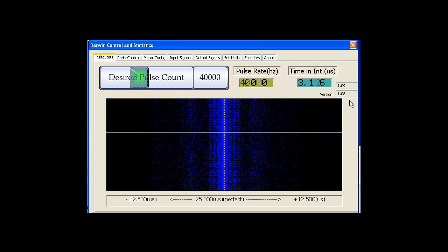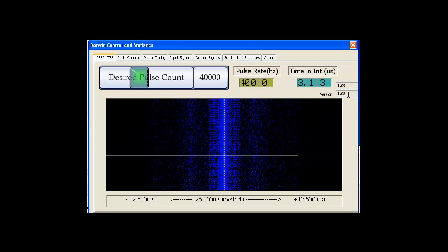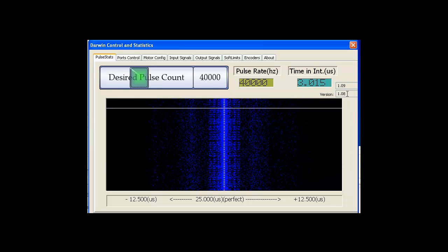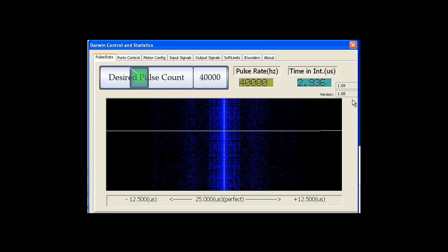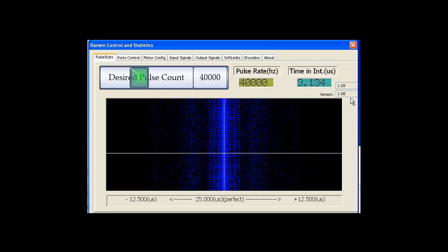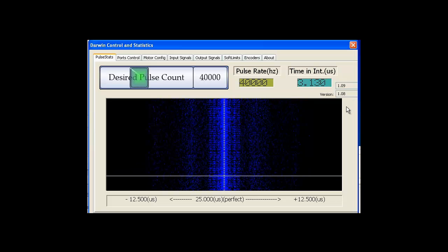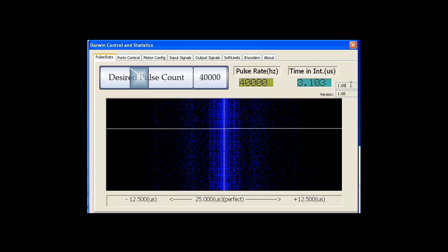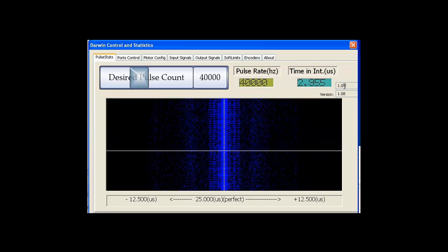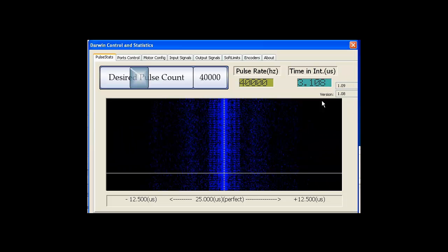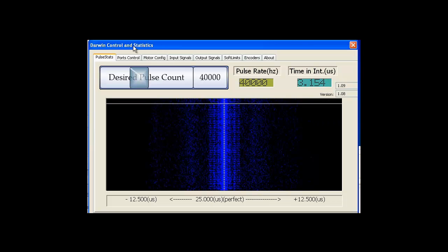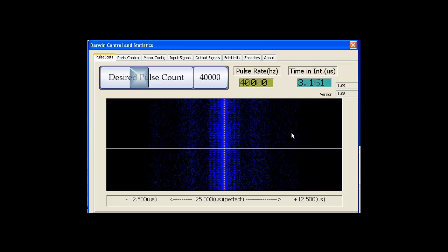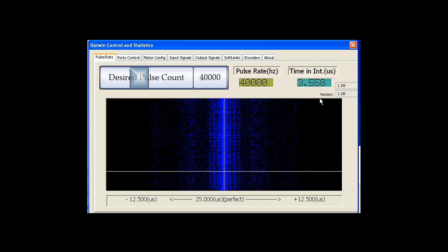We have 2 versions on the screen. You'll notice it says version 1.08 and version 1.09 in this video. That means version 1.08 is the hardware driver, the sys file, which was loaded into your device manager. 1.09 is the DLL, which is the marshalling program, which allows communication between a Mach 4 plugin and the sys file. It also controls these diagnostic and configuration pages.